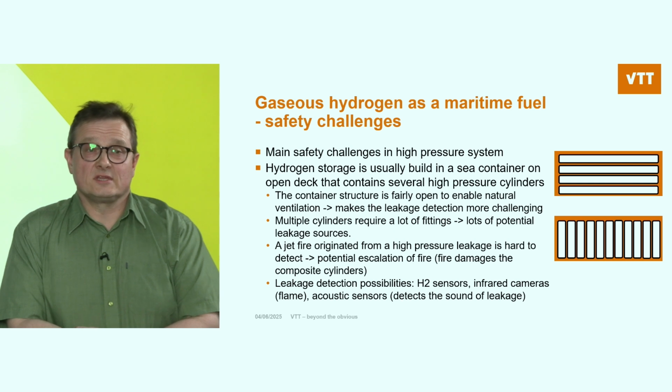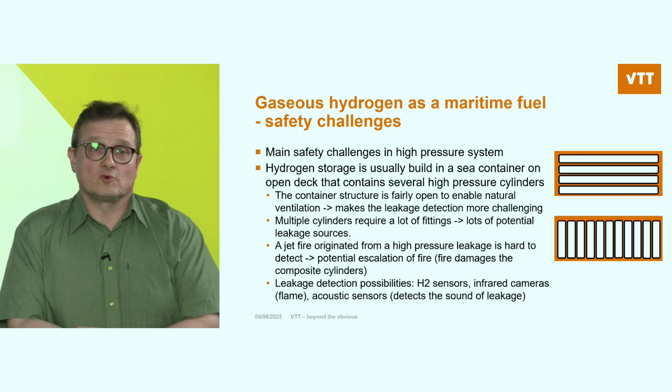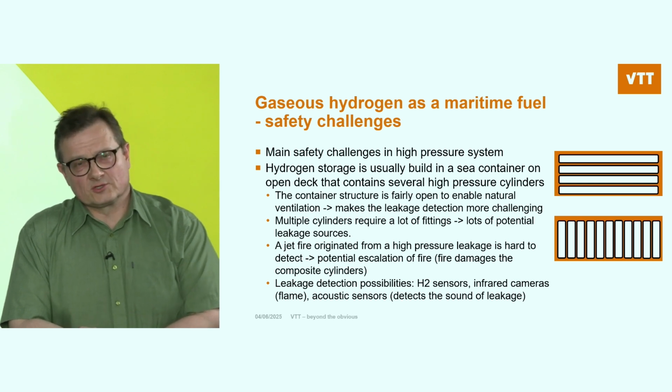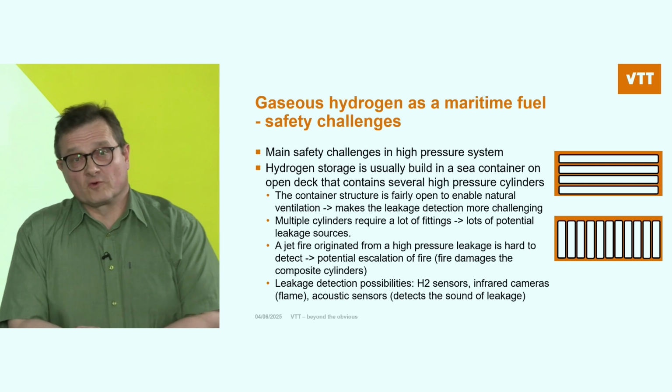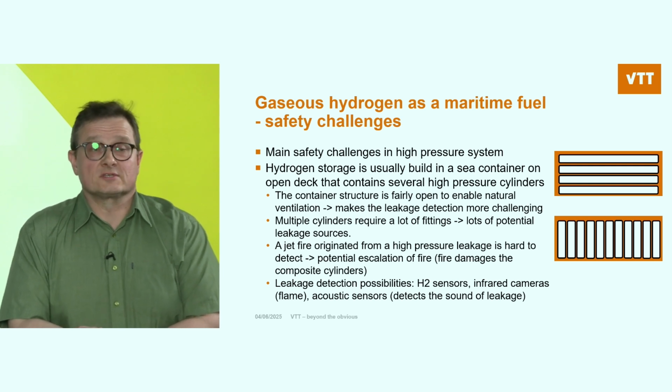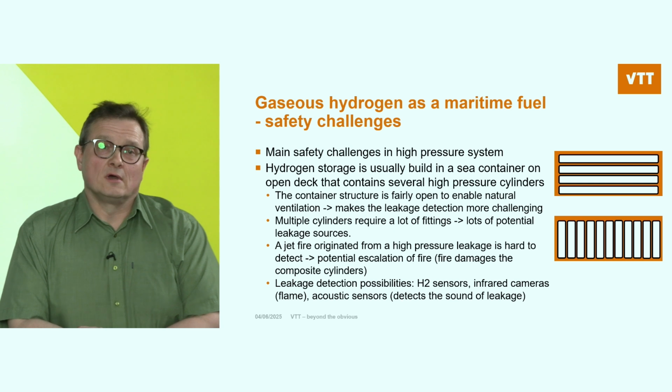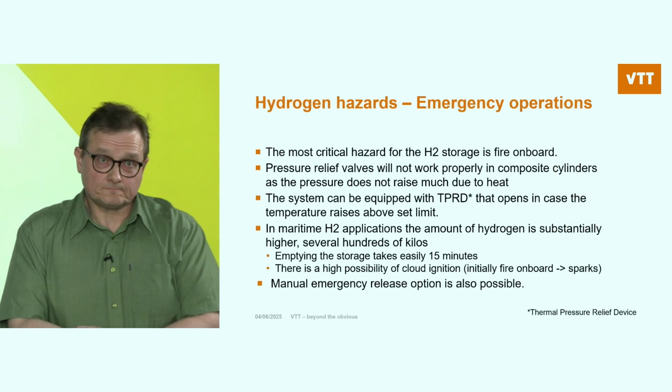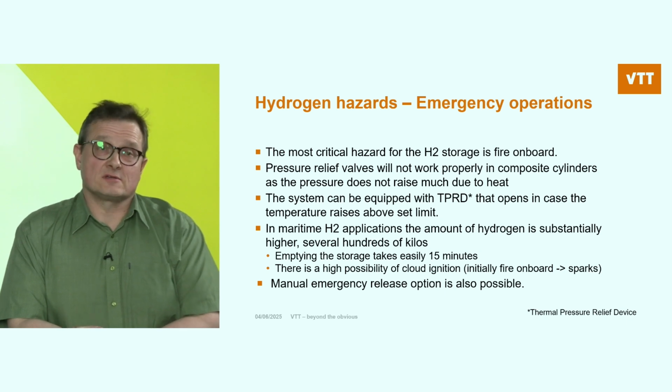There are leakage detection possibilities, of course: hydrogen sensors, but they are not that applicable in open deck conditions, infrared cameras for flames, and also acoustic sensors, which detect the sound of leakage. And the most critical hazard for the hydrogen storage on board is fire.